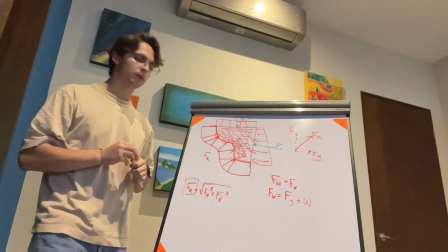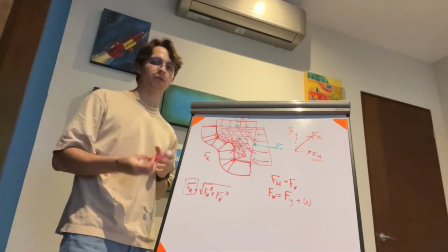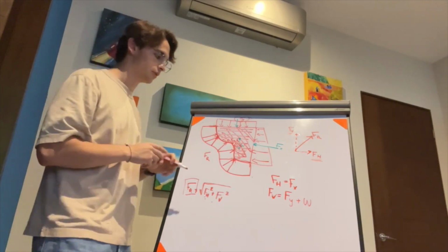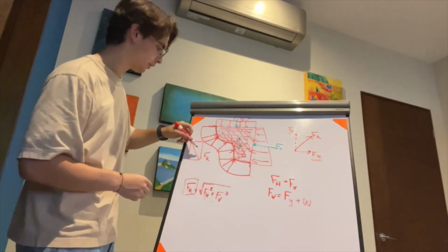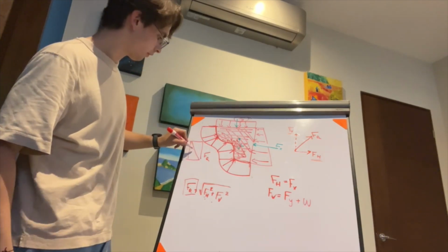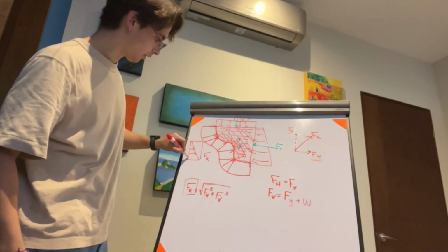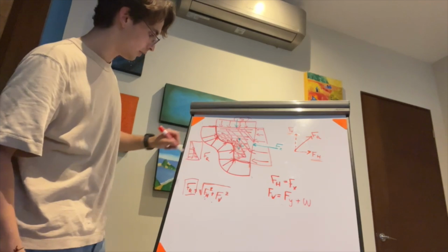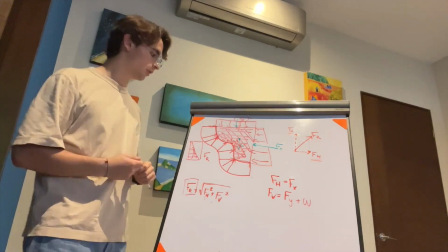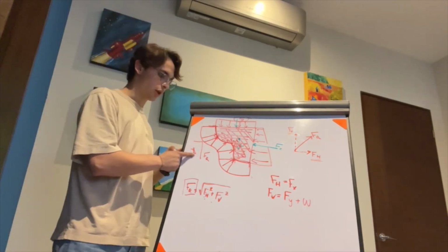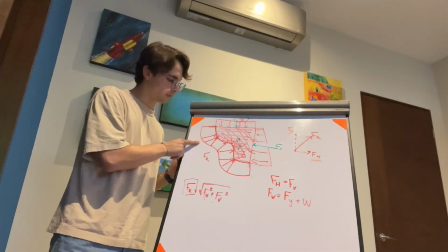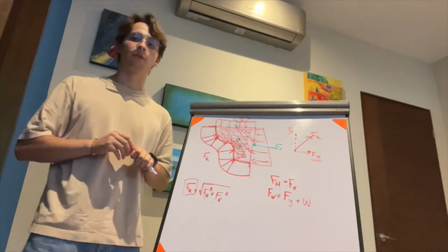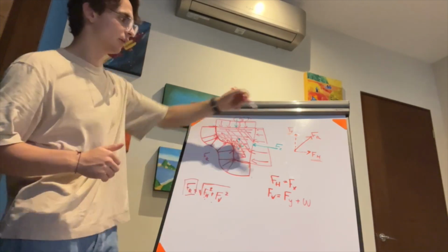In order to analyze the hydrostatic forces on a curved surface, this gets a bit more complicated, since now you don't have just the surface like a tank or a wall or a dam in which you will have these hydrostatic forces acting vertically or horizontally. You have a much more complex shape in order to integrate. And an easier way to do this is by separating the resultant force into its vertical and its horizontal components.